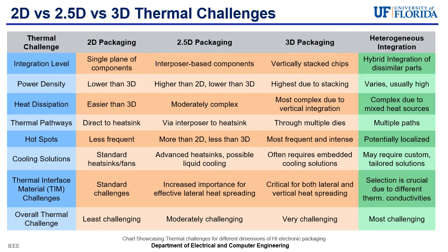Heterogeneous integration, which involves combining different types of components like memory and logic into a single package, increases these challenges, particularly in 2.5D and 3D packages. Managing the different thermal characteristics and requirements of these diverse components adds a level of difficulty, requiring innovative thermal interface materials and dynamic thermal management strategies to maintain device performance and reliability.